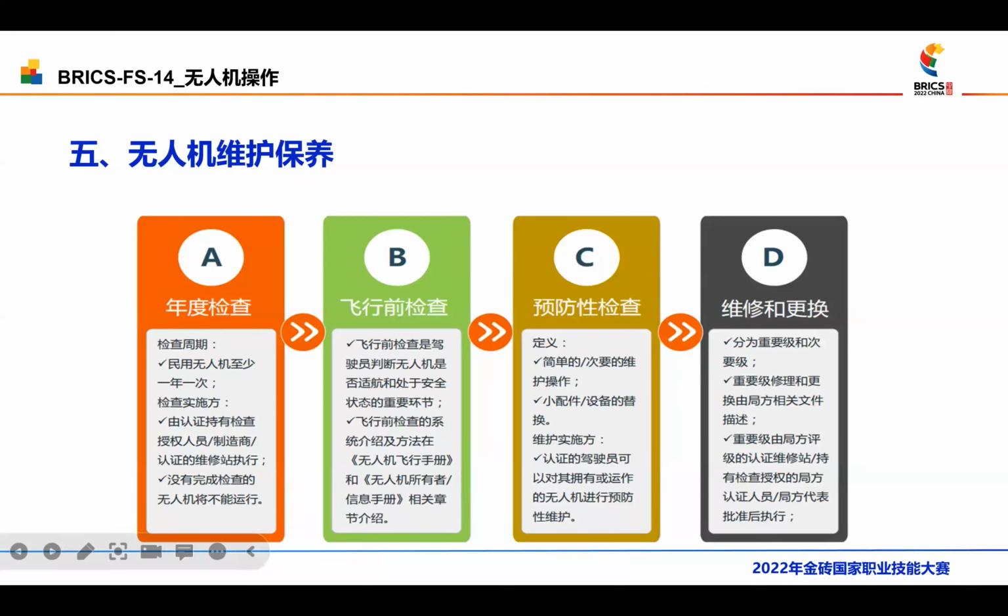So in order to deal with different types of emergency or critical situations and emergency procedures, we should establish a simple checklist to describe the recommended operations. After the UAV crashes, casualties, or mission failures, we should analyze the reasons for improper operation, equipment failure, or environmental interference. Based on these reasons, we should analyze whether the situation is critical or emergency, and finally find out the basic countermeasures according to the checklist.